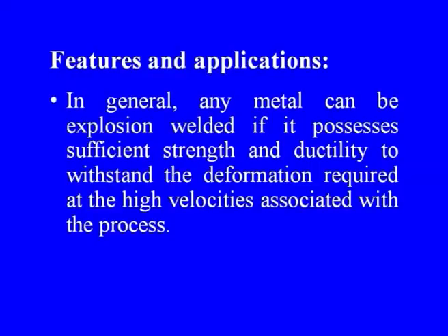Now, let us see different features and applications of this process, the explosive welding process. In general, any metal can be explosion welded if it possesses sufficient strength and ductility to withstand the deformation required at the high velocities associated with the process.